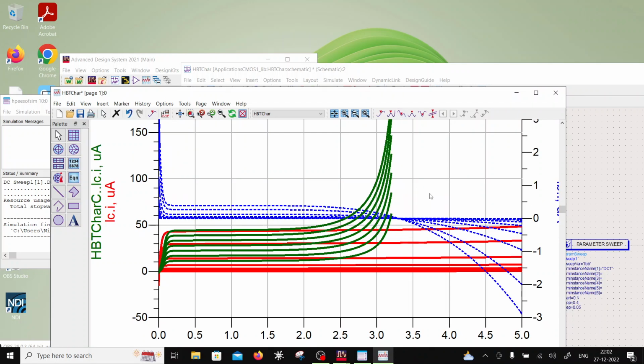Okay, but the breakdown voltages are going to be less. Or you can also say that the device can be more linear in the forward active region when biased with a current rather than biased with a voltage, or the gains would be higher. So I hope you understand what I'm saying. The issue is the breakdown voltage has drastically dropped. It is the collector to base breakdown with emitter open divided by nth root of beta. If nth root of beta, n is 4, roughly it will be half. So if the breakdown was at around 5, you are going to see the breakdown around 2.5, half of it,